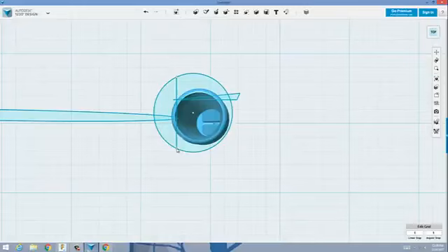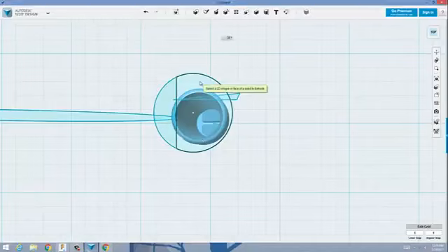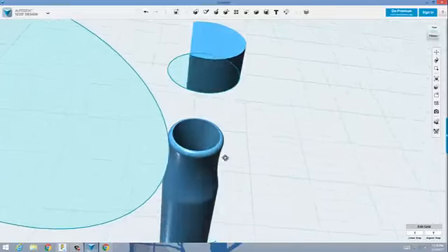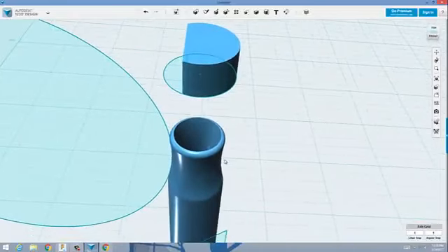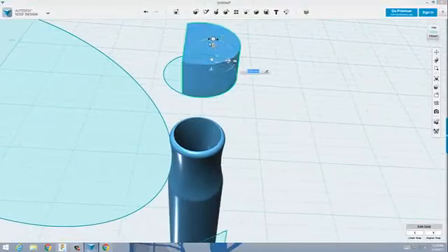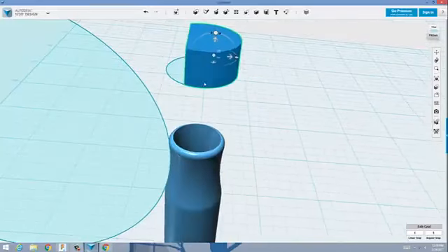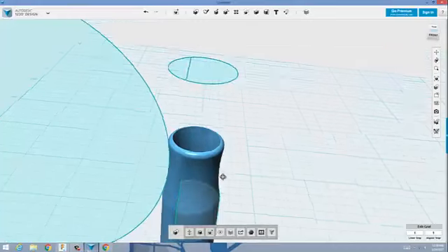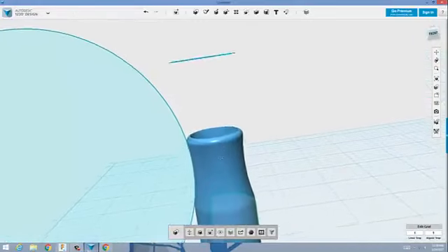Click, exit that mode. Now I'm going to extrude this portion of my circle, so I'm going to hit my keyboard shortcut, and I'm going to extrude that up 6 millimeters. Notice how I've got a little block. I'm going to move that down along the z-axis, and I'm going to move it down negative 35 millimeters, and now it is inside my whistle.